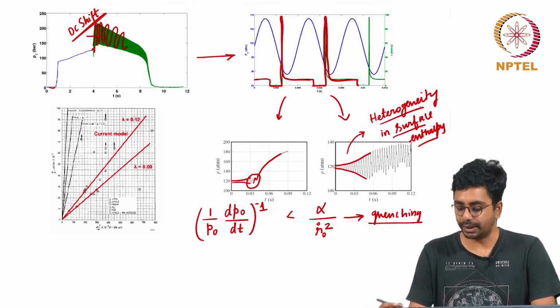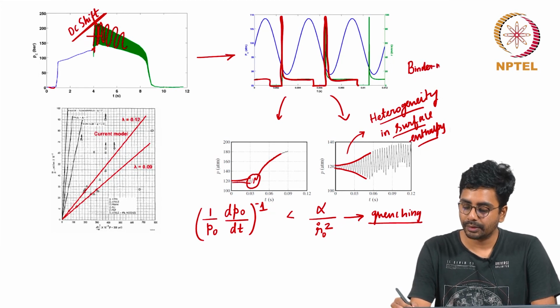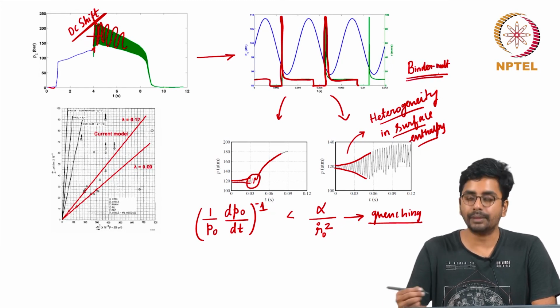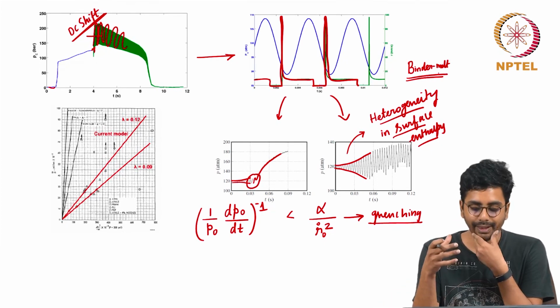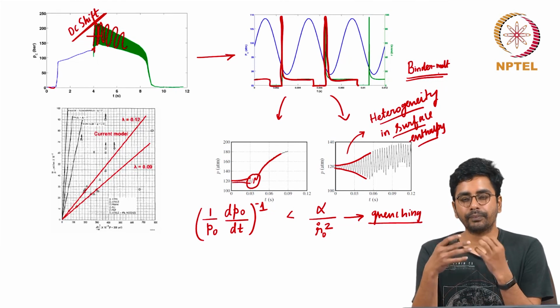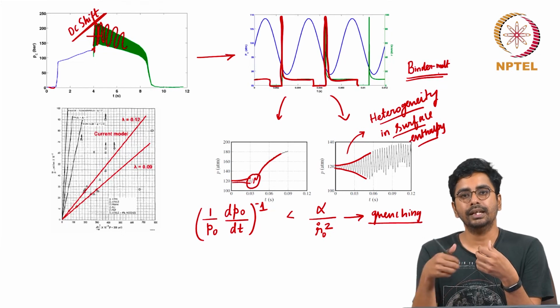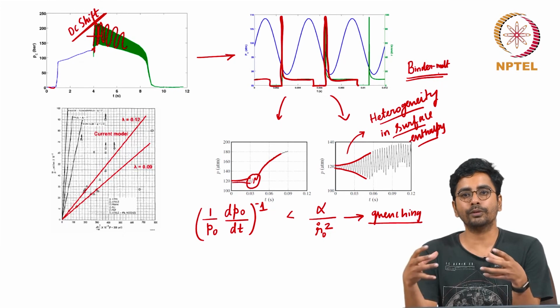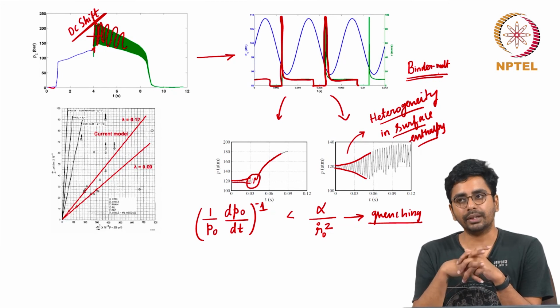To put it in simple terms, it is the binder melt fluctuation. You have AP surface surrounded by binder, and instability is usually associated with the use of burn rate inhibiting additives, and these inhibitors, because they are added to the binder, inhibit the gasification of the binder, leading to overflow of the melted binder over AP, causing the burn rate to go down.